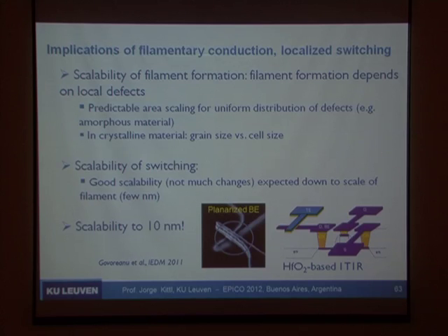What are the implications of this filamentary conduction? One of them is scalability. This is good news for scalability. We want to make these devices very small. If you want to compete, for example, with NAND flash or any of these memories, we have to aim at a maximum of 10 nanometer feature size, and even below that.